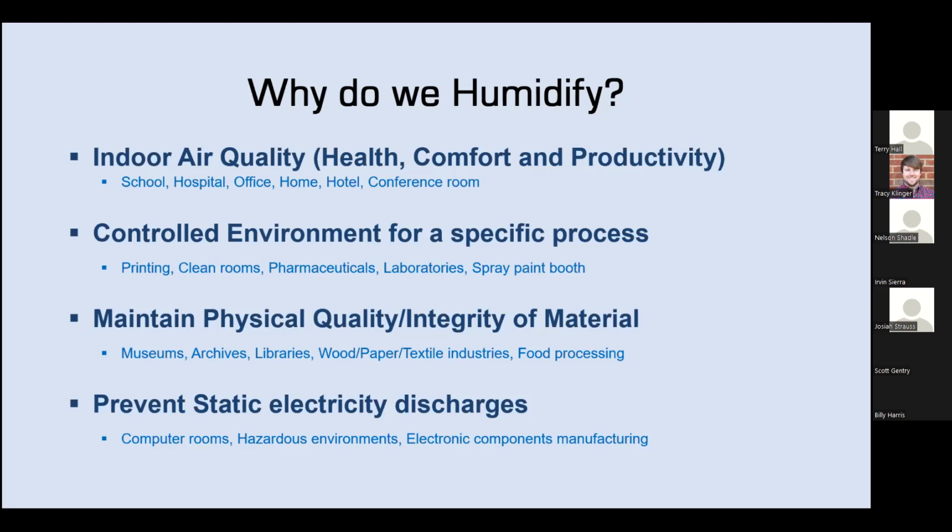And they do this on different levels. There could be not a lot of air exchange or ventilation, because it's mainly just computers and very few people. Or in some applications, they use a lot of ventilation and put the equipment in an environment where they can take advantage of free cooling using adiabatic media. An example of the latter would be mining for things like Bitcoin or Ethereum. That cryptocurrency mining uses free cooling because it's more efficient and your return on investment is larger.